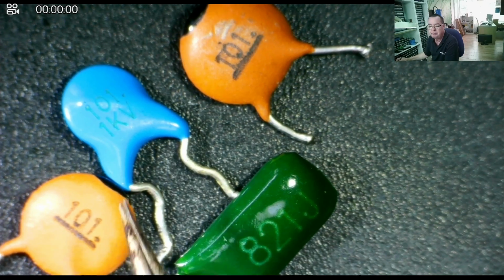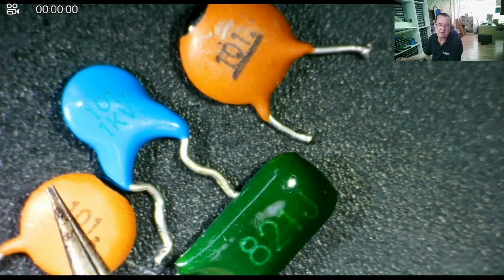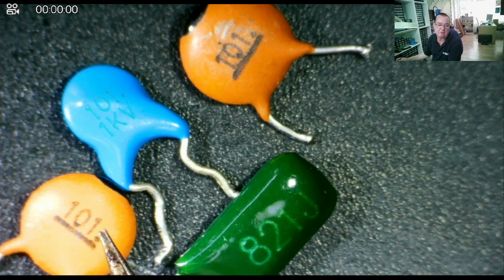But don't be surprised on vintage capacitors to find them marked as 100 if it's 100 picofarads. So if you find capacitors marked 100, the chances are that is not a 10 picofarad. It's not 10 with no more zeros, in other words 10. It is 100. Yeah, and you'll find that on old capacitors. So if you see 820, it's almost certainly an 820 picofarad capacitor. If you know it's an old capacitor, I'd say that is what it is.